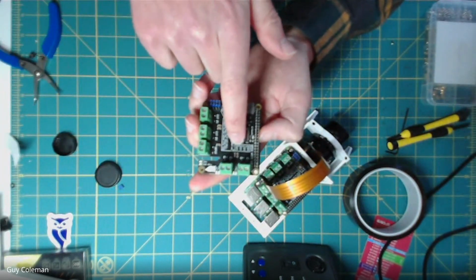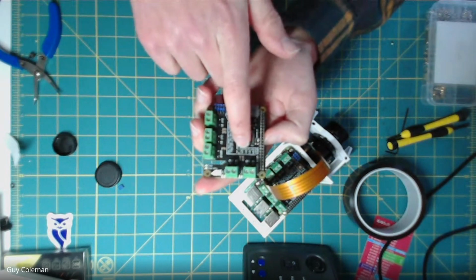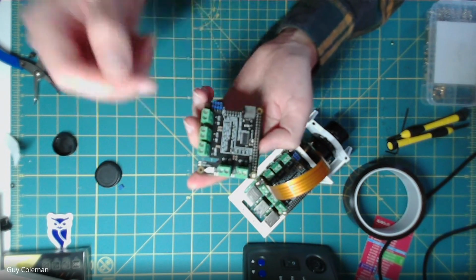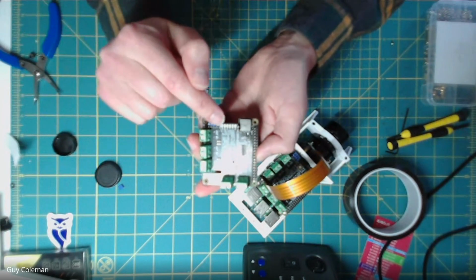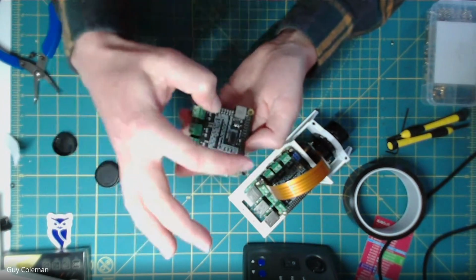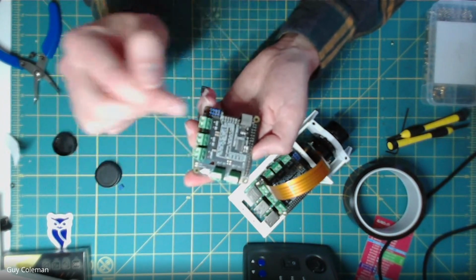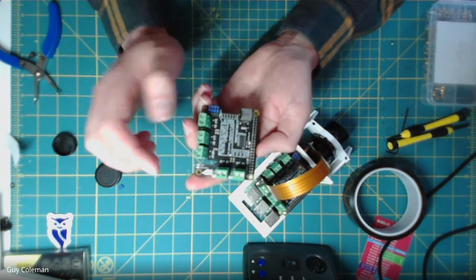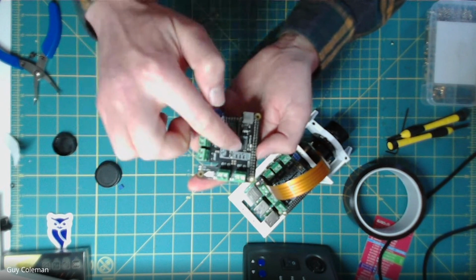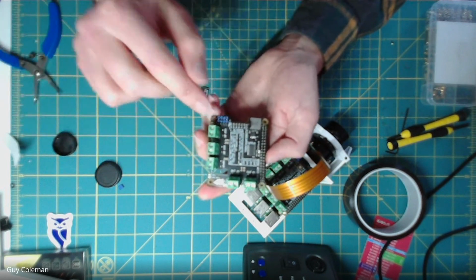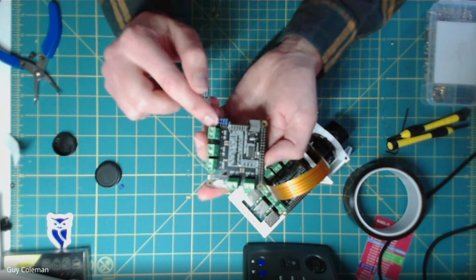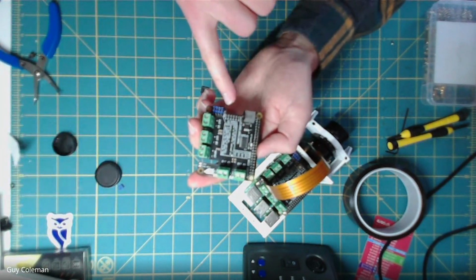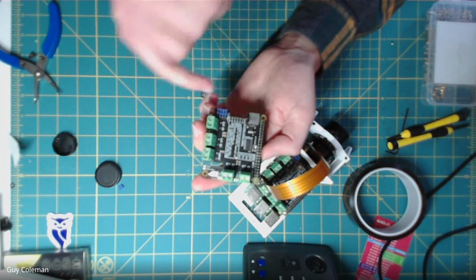So number 1 is GPIO 13 or board pin 13, 15, 16, and 18. That's also in the software. But if you want to use different pins, you'll have to remove these pins here and make the connections yourself between the GPIO and this point. We also have a PWM control on this board as well. So that's the chip here. If you want to use PWM control for each of these outputs, say for PWM-based spot spraying, then you can jump these across further up.